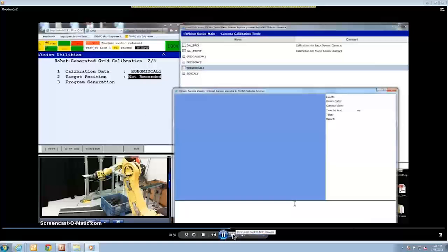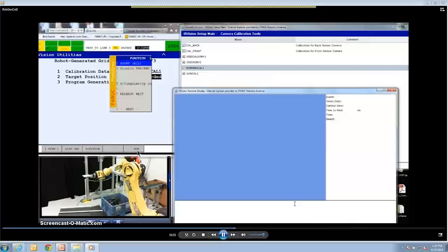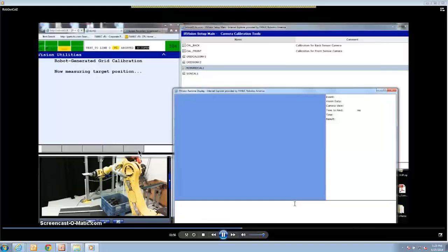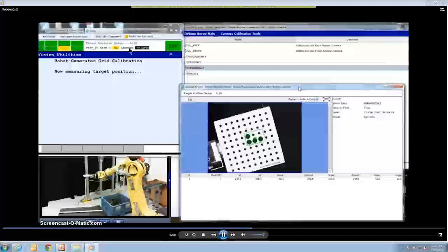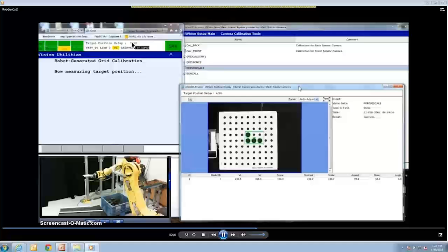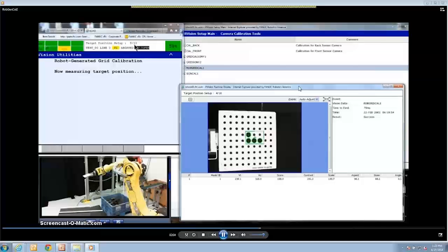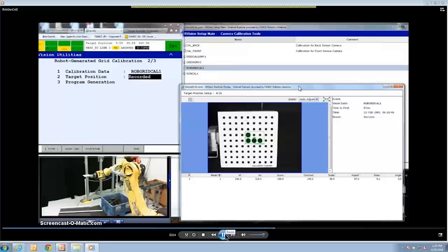So now we're going to do the first step, which is target calculation. We're going to shift run. And again, I've sped this up about 8 times. So here you do get some feedback on what it's done, how many steps, where it's at in the process of calculating the target. So once it's done all its motion, it takes about 3 to 4 minutes. So there we go, that's done. So it's calculated a UTOOL.